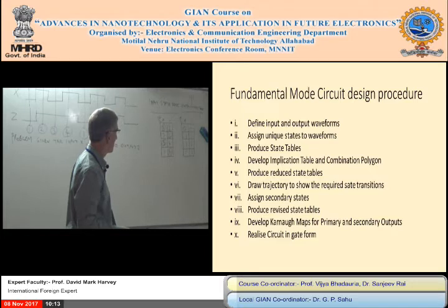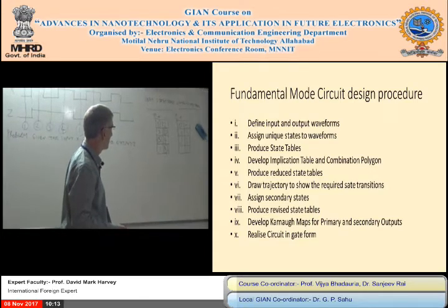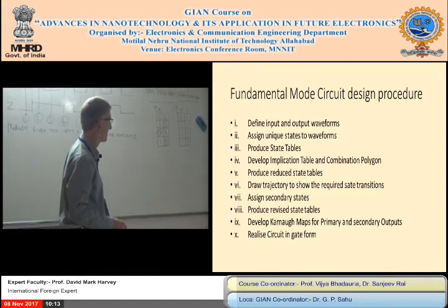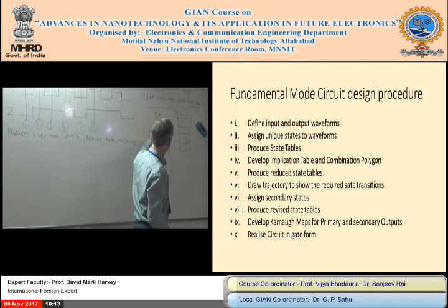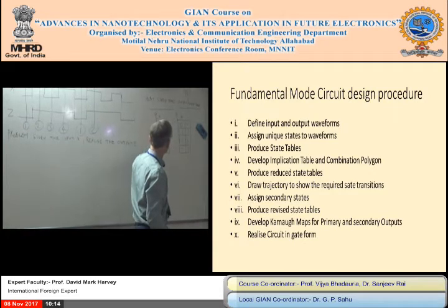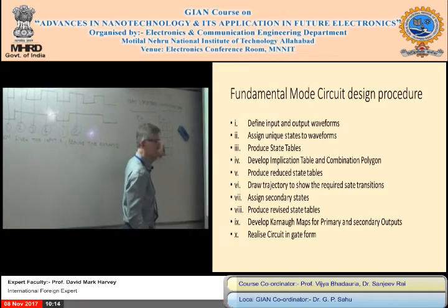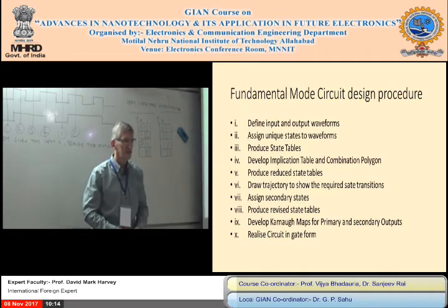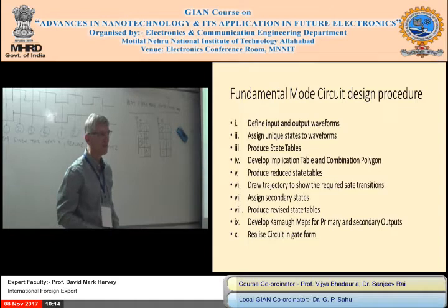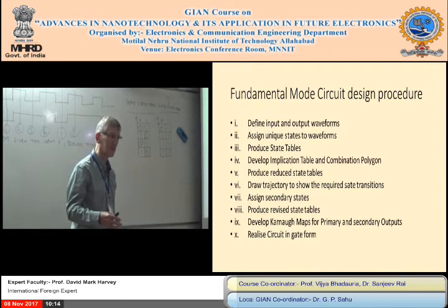Yes, we can do a combination if you've got 2 rows that can be combined under the following 2 stable states with the same output in the same column. Same column means the same inputs. So, for example, state 1 and state 3 are in the same column, but we've got different outputs. So that can't be a yes. If they both had an output of 1, in that column they could be combined, but it has to be for all the columns.